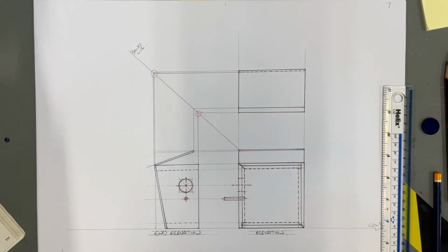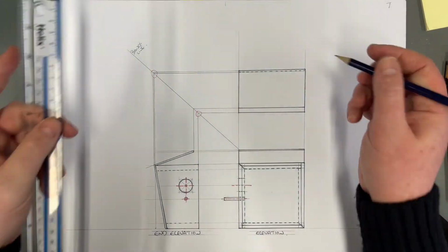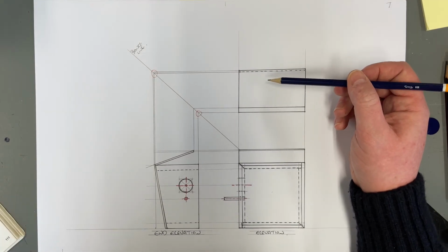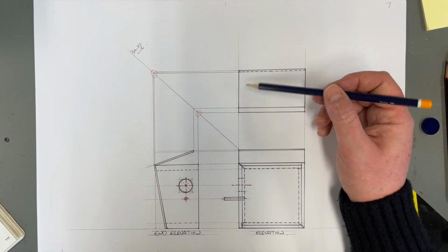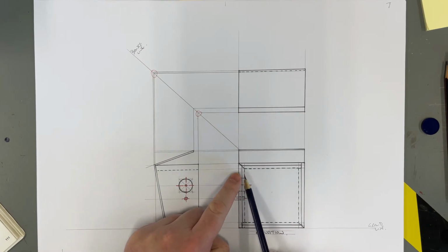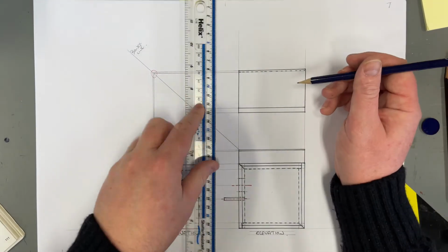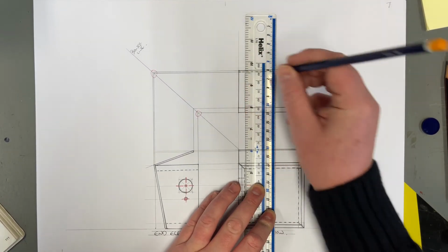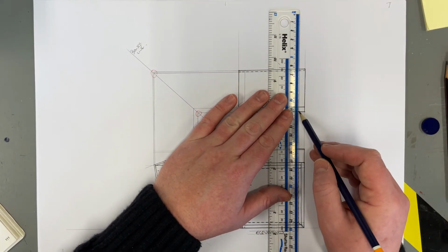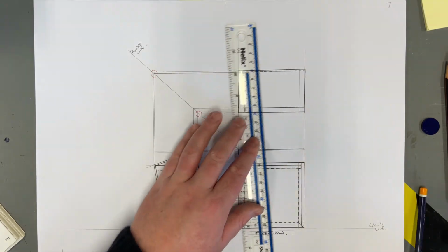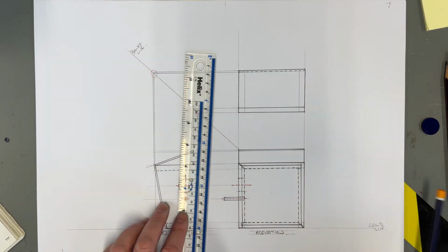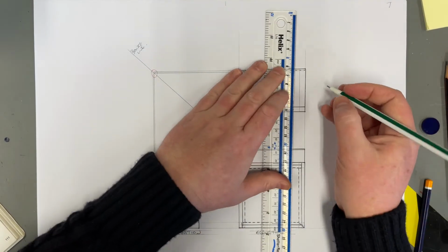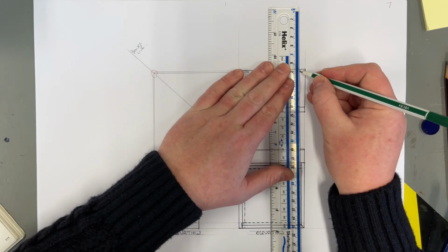So I'll put the birdhouse back out of the way just now. And we're going to think about what we would see in terms of material thickness. So looking down on the object from above, we would see the thickness of the material here in length, at the left and in right. So both of those would be projected up, like so, like so. And in addition to that, we would show those lines as hidden detail. But again, it doesn't go through the metal, so it would start roughly about here.